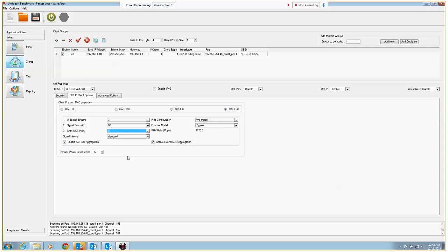And so often you have customers who have set their signal power very low, or they have configured a client type here that's not compatible with the access point, and they'll complain that in the upstream direction, no frames were ever received, no frames were ever transmitted. That's because whatever you set up here is exactly what that client is going to use for transmitting data. It does not rate adapt.